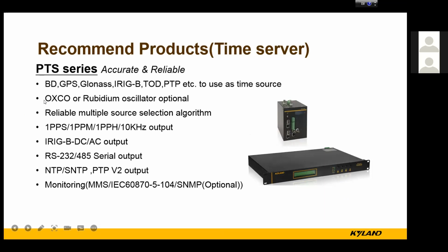Besides, we also support different levels of oscillators: OCXO and Rubidium oscillator. The Rubidium oscillator has higher holdover performance. There are multiple outputs based on different models. We also support different protocols for monitoring, and we also support MMS inside the substation.